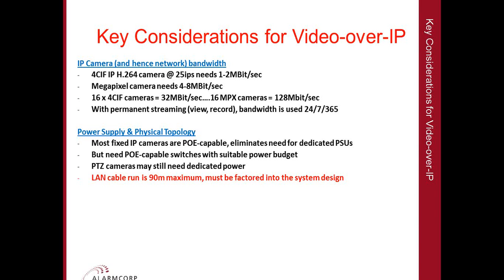In other words, if we plan on connecting 24 cameras to a PoE switch, can this switch supply power to all cameras simultaneously? Now most good switches will, however some switches will say on the data sheet, oh, you need an external power supply to achieve this. Now, most PTZ cameras will still need dedicated power because their power needs will exceed what's possible over PoE.